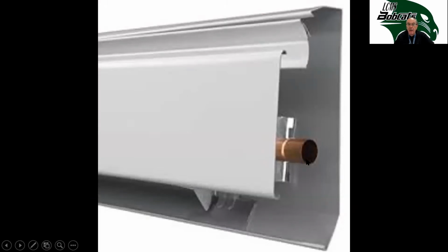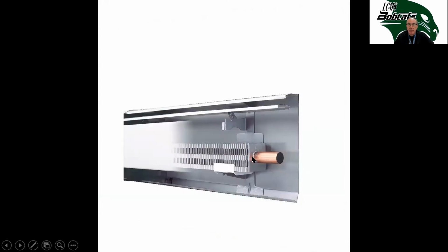Here's kind of a cutaway where you can see this copper pipe that'll carry the hot water behind this thing to heat those metal fins up. And here's a little bit more cutaway. The copper pipe is going in. These little pieces of aluminum get really hot. The air around them warms up. Hot air rises and makes a convection current in the room.